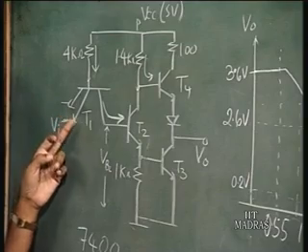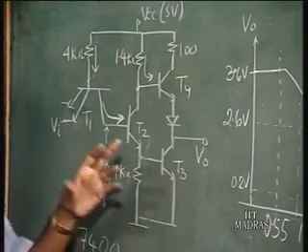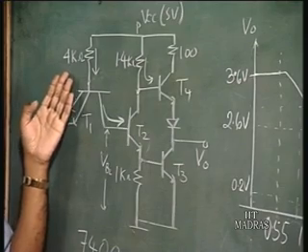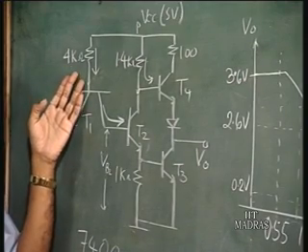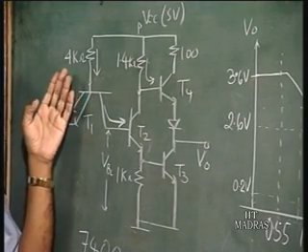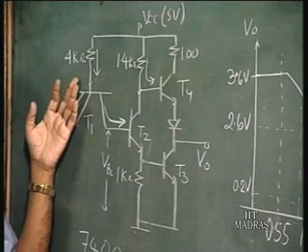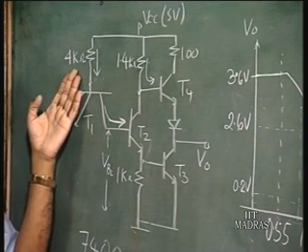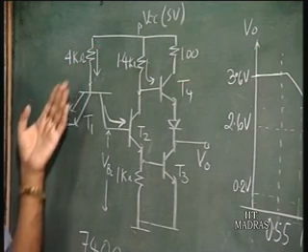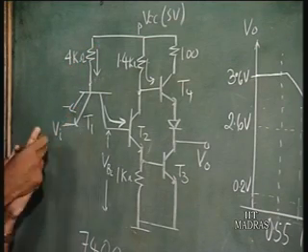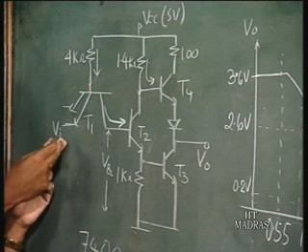But of course, they give a somewhat higher current, because in IC technology, the resistances cannot be fabricated with such definite values. There is always a tolerance. So, if the resistance is much less than 4 kilo ohm, the current is going to go up. So, they say that the maximum input current when the input is low is 1.6 milliamperes.